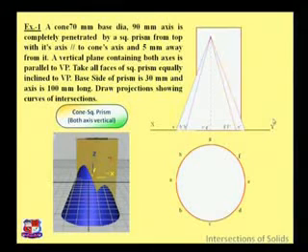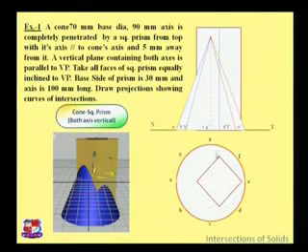Name these points, and at a distance of 5 mm from this axis, mark another axis, and from that axis draw a rectangle like this. This is a square because it is given that in the top view all faces of the square prism are equally inclined to the vertical plane. Hence this square should be drawn like this.